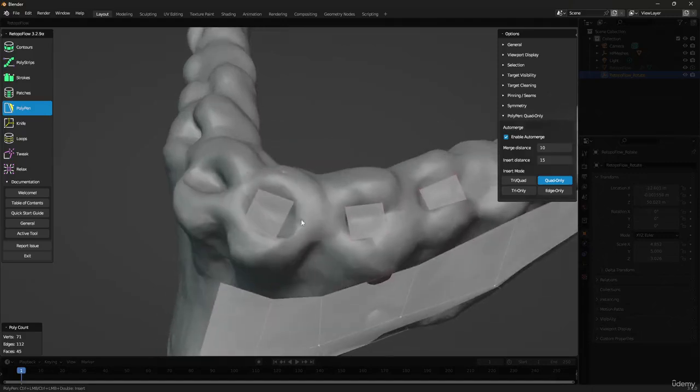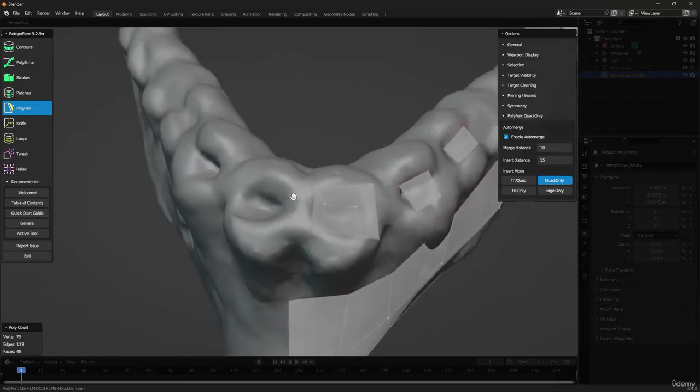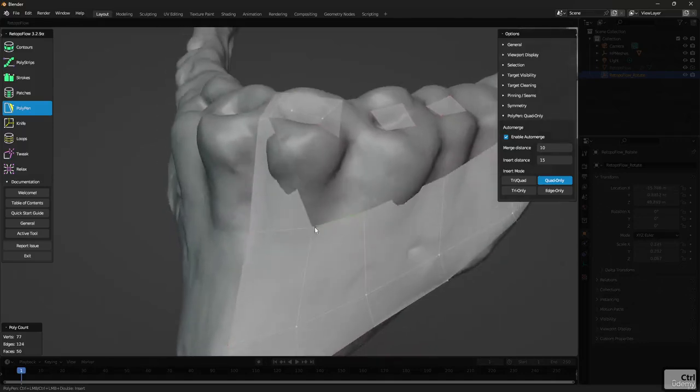There we go. Now from this, guys, we're going to do a similar thing. Remember, we grab the edge, we go out, we move this edge in, and then we move it out, and then we just grab two of these vertices and we get them close together. In a very similar way to how it works inside of Maya, when two points are really close to each other, they will immediately snap. We also want to keep following our rules. Remember, we have a middle section or a middle line. So in here, I'm going to try to be very careful to keep a middle line. That middle line is probably going to go all the way down here.